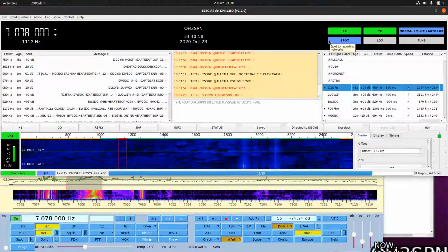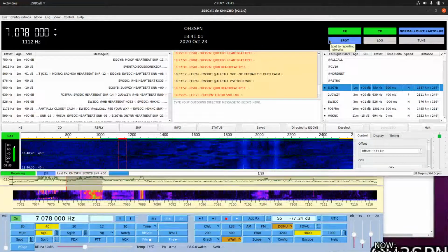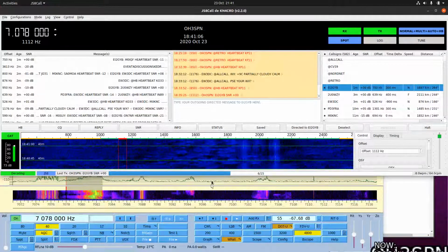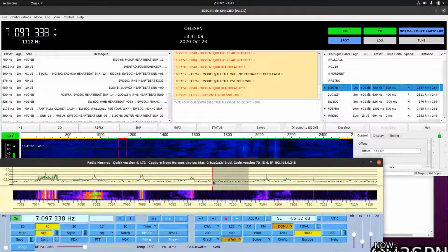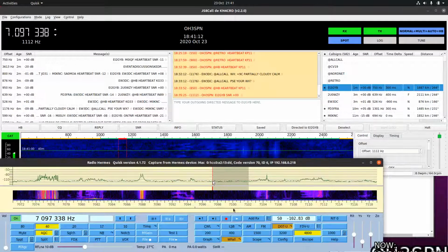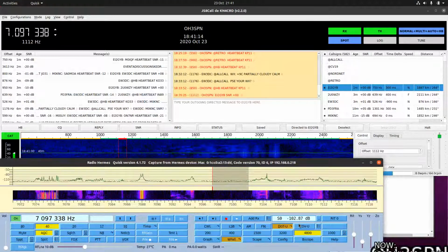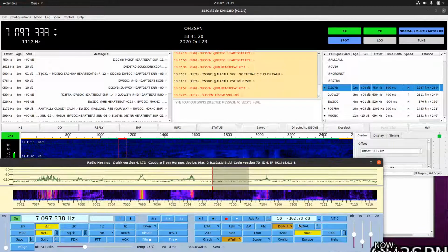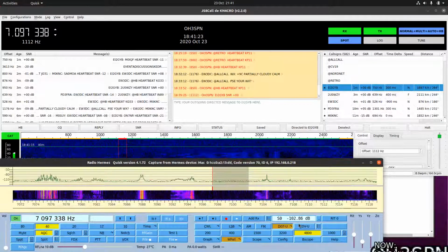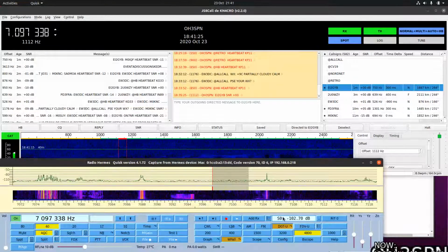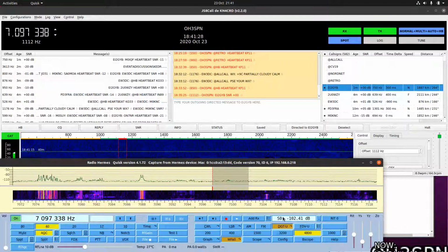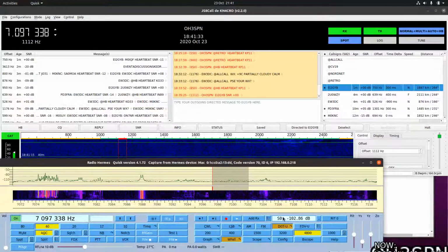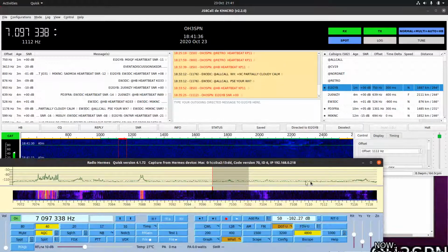Let's see. If I disconnect the antenna... What's this reading here? On JS8Call... It's probably better if I go to a quiet point of the band. Right. Yeah, so I vaguely calibrated the S meter on Quisk. It's very, very roughly calibrated, so don't read too much into it, but it's reading minus 100 dB, thereabouts, minus 102 dB. If I now disconnect the coax, I've now got a signal right in the middle of the bit that I was using as a reference point.